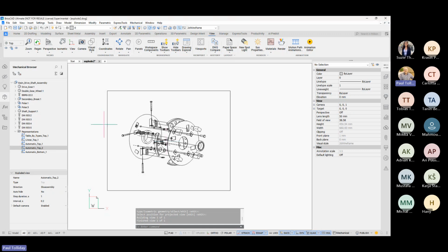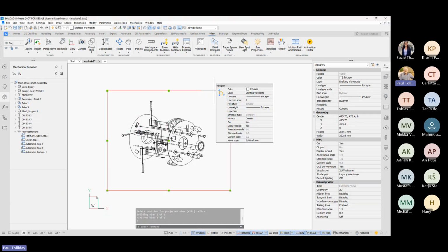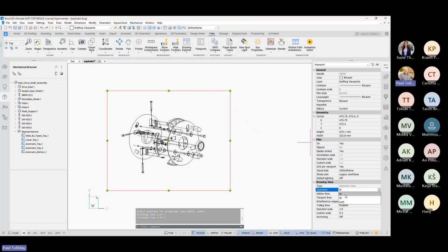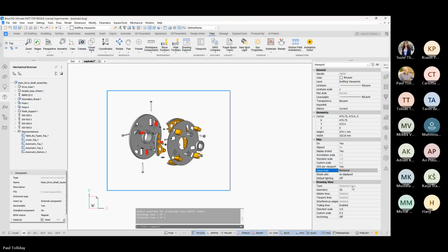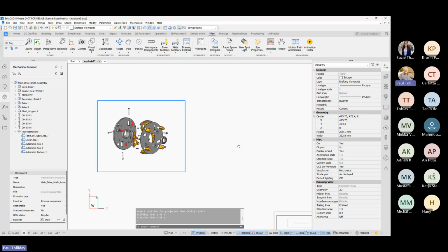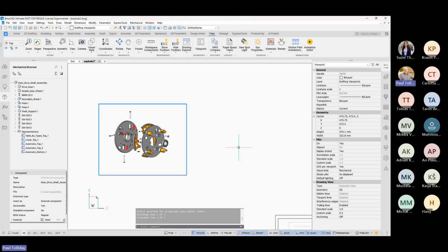Now there is one thing to show you, sort of a workaround. Our trail lines are visible when we're in the 2D environment. So if I select this now and do what I did before, you might want a 3D rendered version of this. So I'm going to change that to 3D. And I'm just going to change the view to mechanical. As you'll see, the trail lines have now disappeared. They're not available when you're in the 3D mode. Now, there's a way around this. I don't like using the phrase too much, but it's sort of a workaround we can do for this.